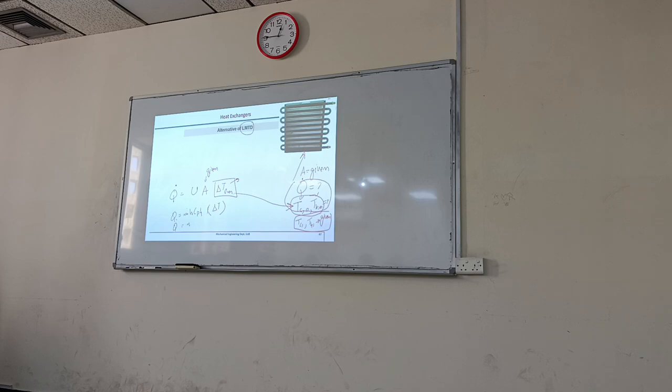The same Q dot is equal to M dot C CPC delta T, and from here you will write an equation for THO, TCO, whatever you assume. So you will be doing iterations. We can use the same method, but here you need iterations. Okay. So we define one temperature, one water temperature. We find it for Q equivalent. Yeah, okay, that is also fine.